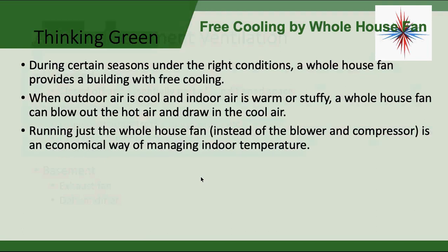During some seasons, under the right conditions, a whole house fan provides a building with free cooling. If you think about your area, I call them the shoulder seasons: early spring, mid-spring, late spring, where it's still cooler, and your house warms up. We can actually use a whole house fan to blow out the hot air through the attic and draw the cool air in through cracked windows on the bottom floors of your house. Free cooling. Running a whole house fan instead of a blower and compressor is a much more economical way of managing indoor temperatures. We do the same thing in commercial cooling.